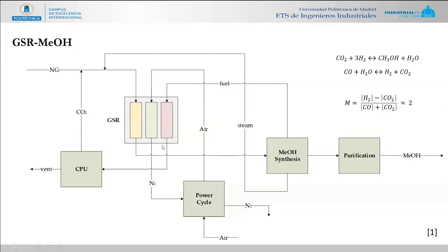Once the fuel is combusted, we have reduction gases, cool down, remove the water, we purify the CO2, right, which is then routed back to the natural gas stream, and of course there is a small bleed. But this system allows a very high carbon efficiency, minimizing the emissions relative to conventional methanol processes with autothermal reforming. We need a purification because there is some mixing between the outlet feeds, if you regard the temperature profiles, sorry, the reactor profiles. And finally, with regards to the air stream, we just have a power block integrated.